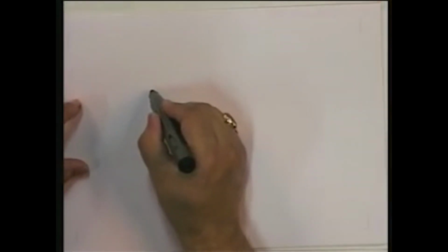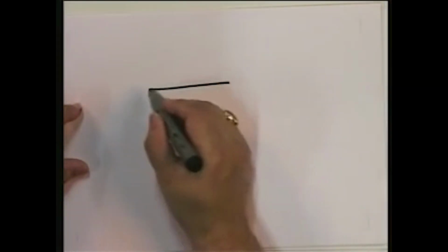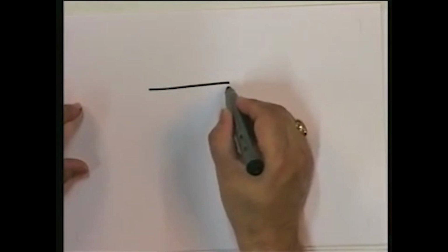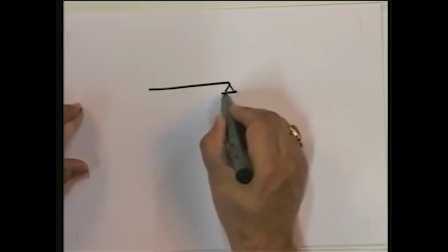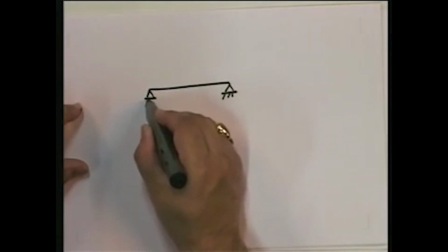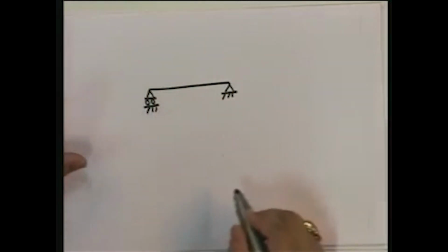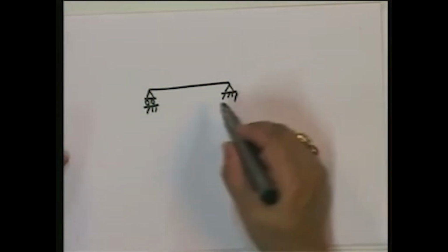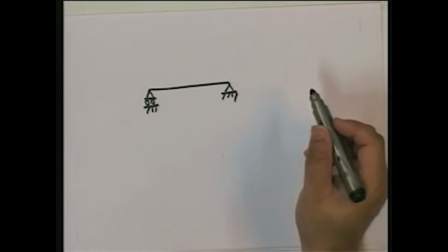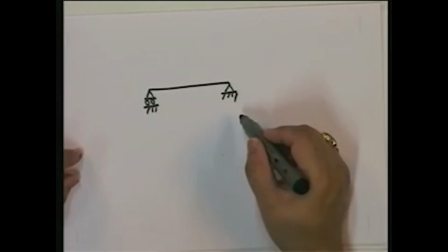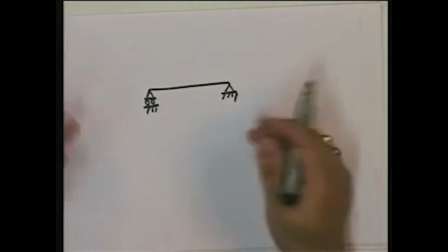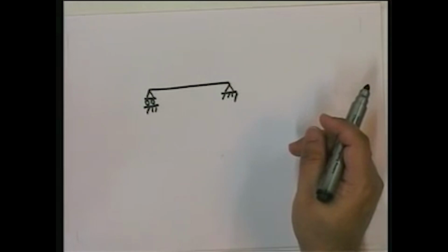Now, let's move on to that for a frame. Well, before I go for a frame, let me start off with a simple one, which is a beam. Let me look at a very, very simple beam. This is a structure that you are all familiar with. What is this? A simply supported beam. What is the static indeterminacy of the simply supported beam? 0. You know that. It's a statically determinate structure. But now we are not looking at static indeterminacy. We are looking at kinematic indeterminacy.